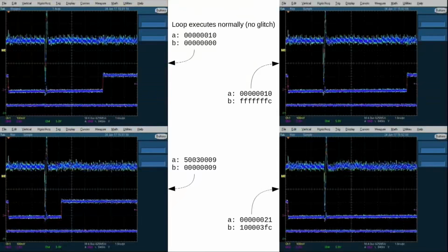And here we have screenshots showing the different results that we have when we glitch at this timing location versus the first one. So we've waited through a couple more rounds of the for loop. Now something else that we can notice in these images, if you look especially at the top left image, you can see when the for loop executes, and we can see a little pattern there, and that pattern we see repeating exactly 16 times. So from the power analysis, we don't necessarily know what instructions execute, but it really is very clear that there's a for loop that's executing exactly 16 times.